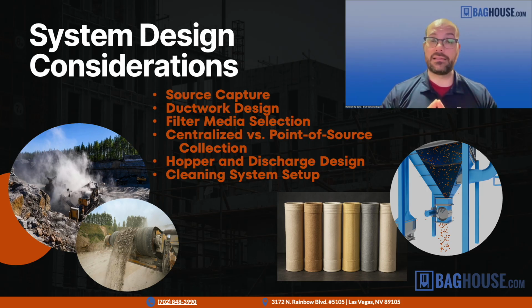And then finally, one last thing that we often see when we do inspections is the cleaning system setup. Most, if not all, modern dust collectors in these applications are going to be pulse jet style, where they pulse the filters with compressed air. Many, many times we find plants where they have it set on cleaning just on timer mode. So just clean the filters every 30, 60 seconds, all day, every day.